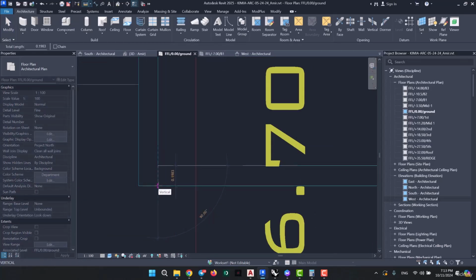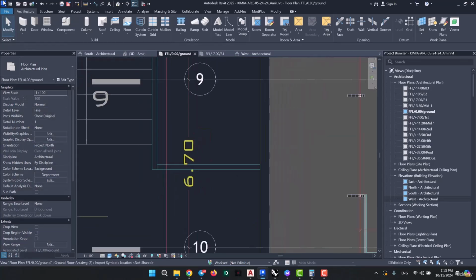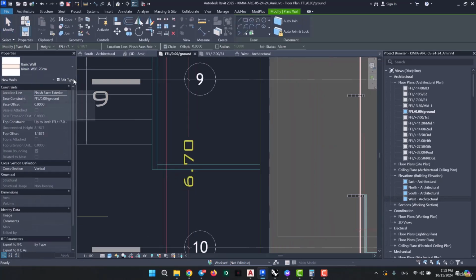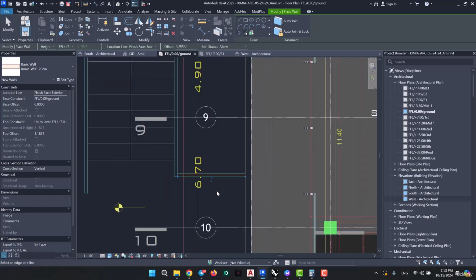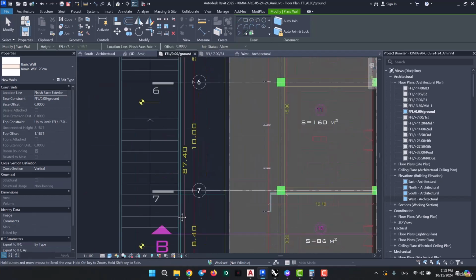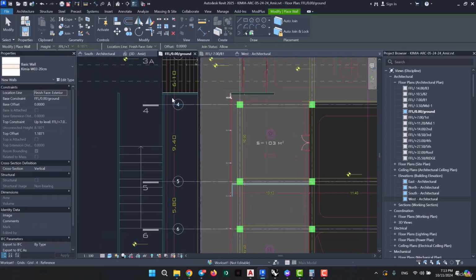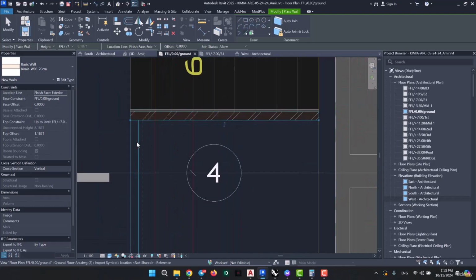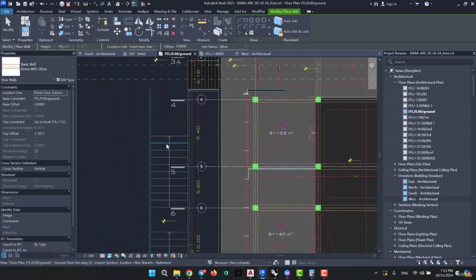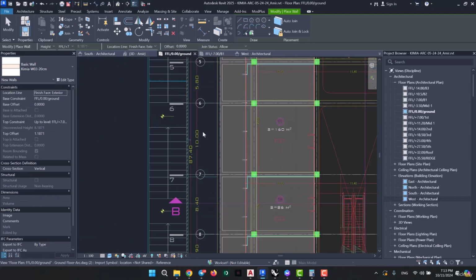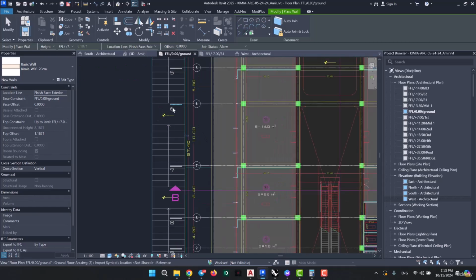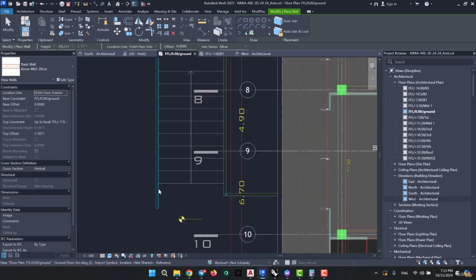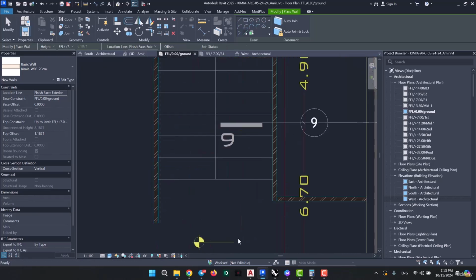And it looks like the walls should be 20 centimeters thick. Now among the types, we've already duplicated a 20 centimeter wall, so we're going to use that same type. And we're going to go ahead and draw the side walls for this garden. Another one should go up here. And then there's this wall on the side, which will also need to be aligned with the slope of the stairs. I'm going to place the other wall and show it to you in the elevation.